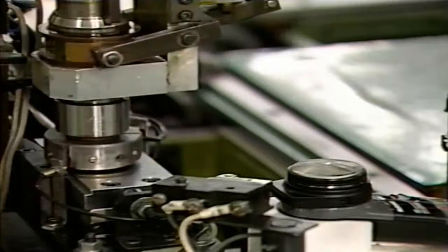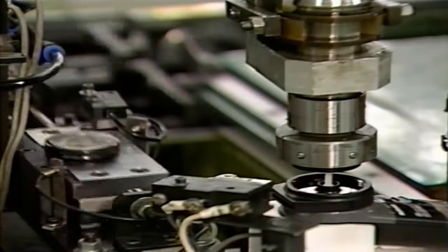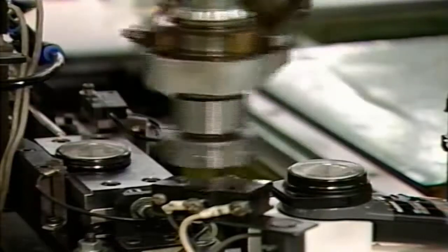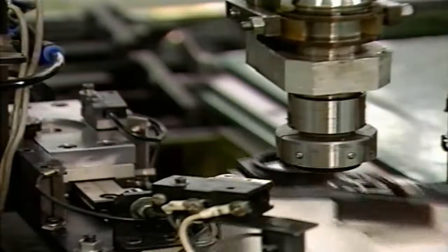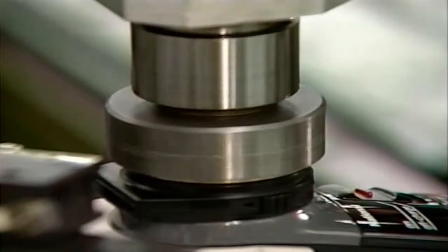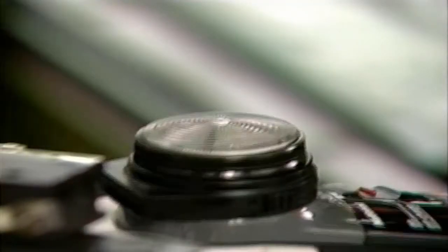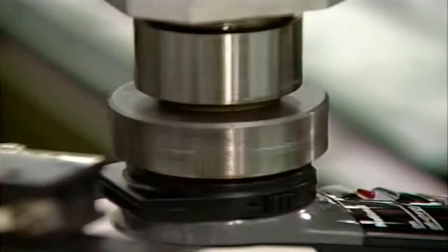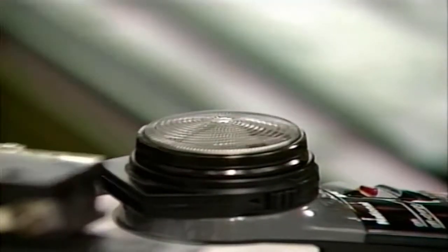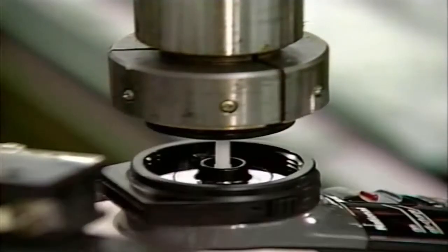This equipment automatically does collet chucking to the functional part of the workpiece and screws it onto the product itself. However, the processed parts have a curved surface, so they are rather unstable. Before improvement, the part sometimes slipped sideways in the chuck and caused short stoppages. Analysis showed that the position of the part was not regular in the chuck. It was clear that if the chuck was at all worn inside, it could not hold the part in a stable position.